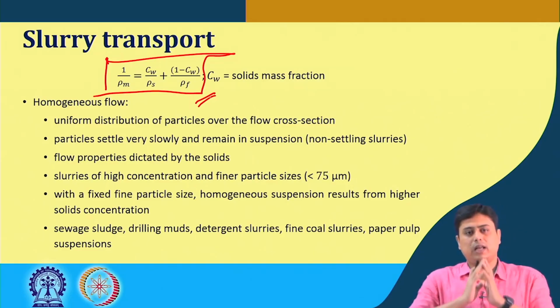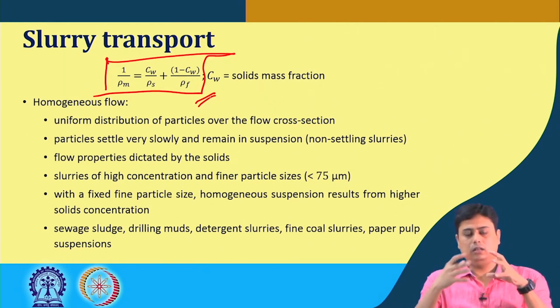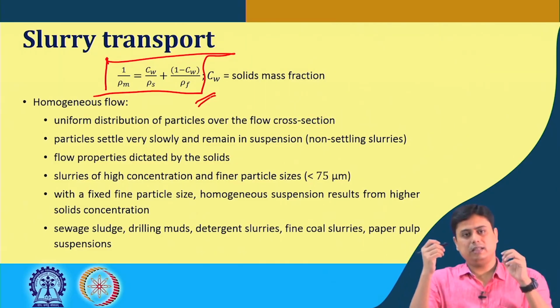Now, when this slurry flows, it flows in different regimes depending on the feed rate or the superficial velocity. Also, these solid particles are basically immiscible and suspended in the liquid phase, and they should ideally remain suspended while flowing.